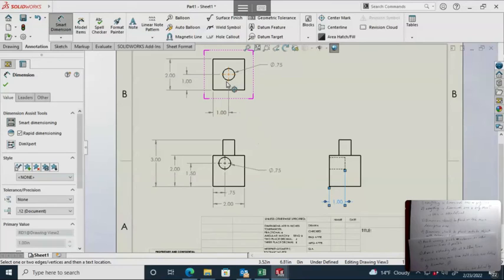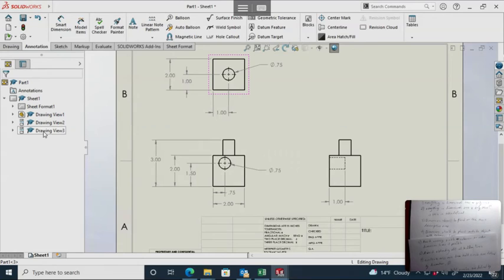And if I made drawing view 3 here, the one up here on the top, if I make it wireframe, you can see that this hole in here is covered up by that peg poking out. So I'm going to turn that back off. That kind of confuses the reader and doesn't necessarily help anything, but this is the more descriptive view. So I'm going to put that hole and its dimension over here on this view.